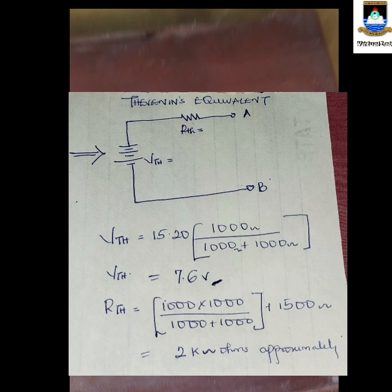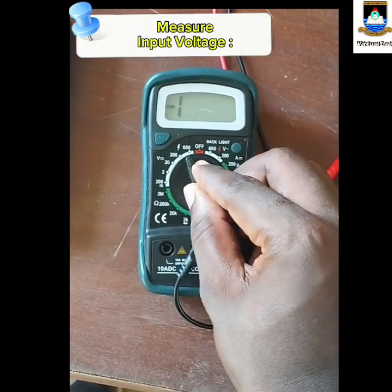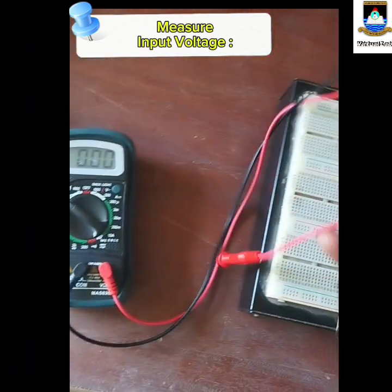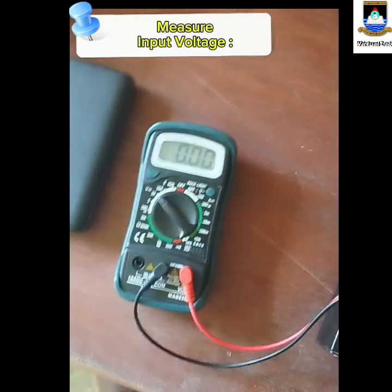So this is the part where we are going to carry out our practical to prove and get the corresponding Vth and Rth. The first step is to measure our input voltage. So switch on our power supply, adjust our multimeter to the DC voltage range, and let's measure our input voltage.